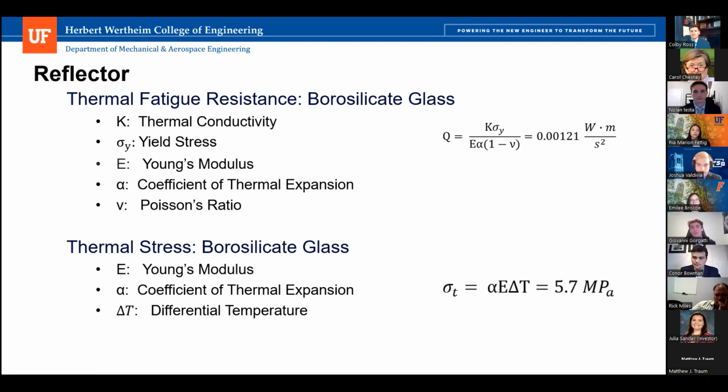And then here's the thermal stress as well, as you can see. And when we compared that thermal stress that we calculated, it was much, much lower than the fracture stress. So we found that that was going to be okay for our design.